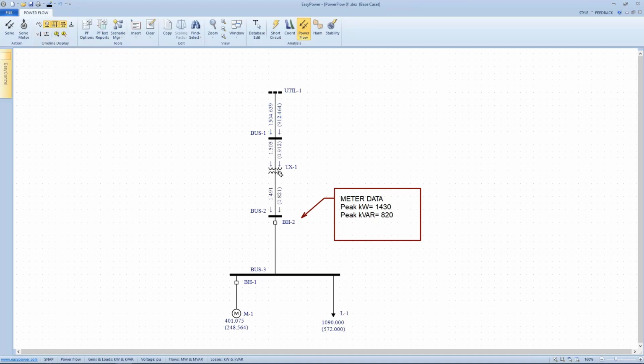So transformers can be a location for loss generation, in which case we would show transformer losses. In this case, it looks like it's about 13 kilowatts real power and 91 kilovars of reactive power. Now, if this was an expanded system, I'd have more opportunity, and the tool gives me the ability to look at the voltage taps, the generator and load draw and demand, and configurations.